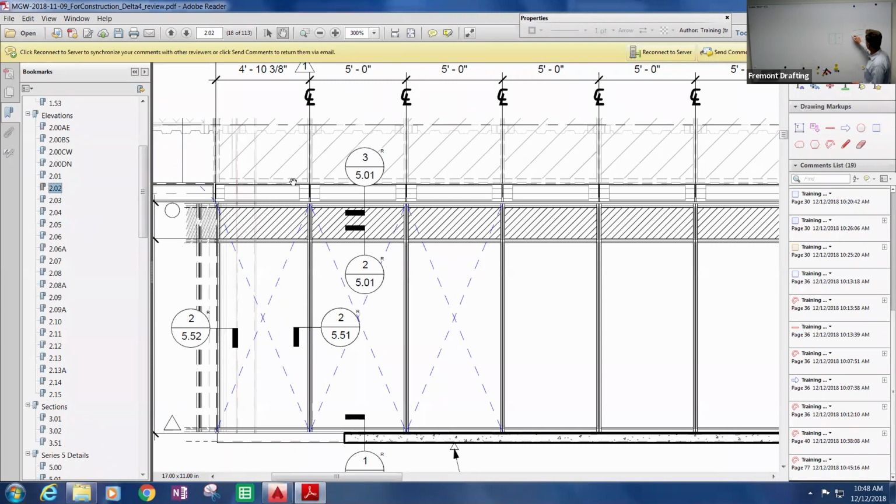So if they're dead loaded on the building here, and then the thing moves, that load, those things just move. Now the element may be hanging off the edge of the building, and then when it moves the other way, it's inside the building. So it's actually moving over. Translating elements usually have fairly distinct horizontal slip areas or slip joints at every floor.